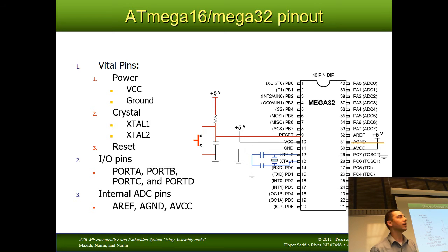We're not resetting. Everything's good. That's a pull-up resistor. When I press the button, current is going to be flowing through this because it's going right to ground. Now, in this case, I've got 5 volts, a 10K resistor, but it's connected directly to ground. All of the current must be flowing to ground.